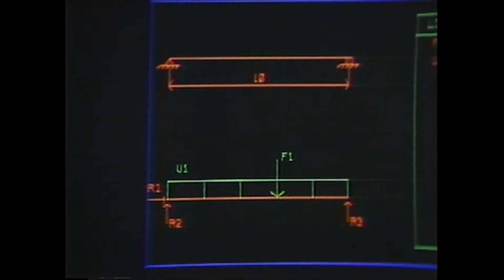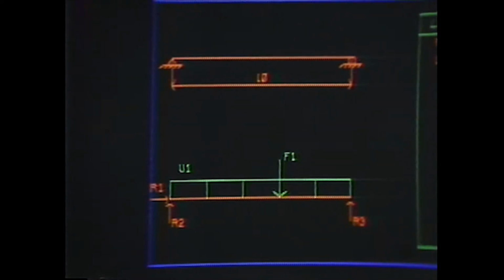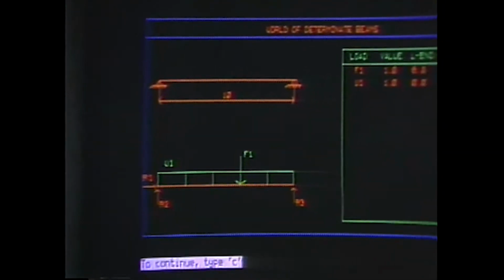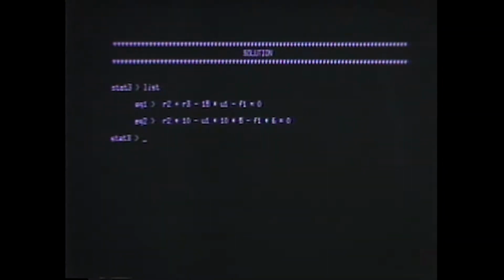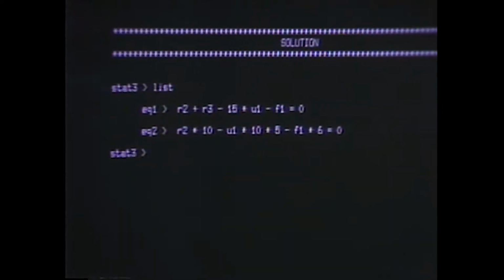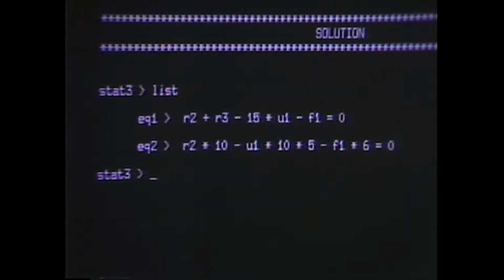What I'm going to do, and I have actually done, is to write in some equations that would help me compute the values of these reactions. And I will show you the form that they've come into the program and demonstrate how the tutor will pick up the mistakes that I've made. The equations which I previously input are 2. One which tries to sum the forces, and one which tries to sum the moments. If I solve them, I'd find out that I'd made some mistakes.